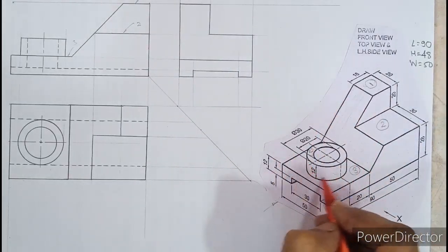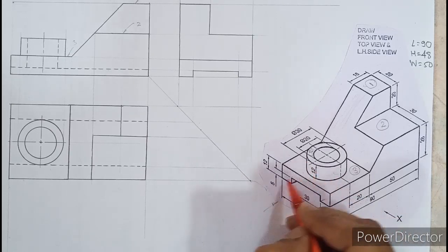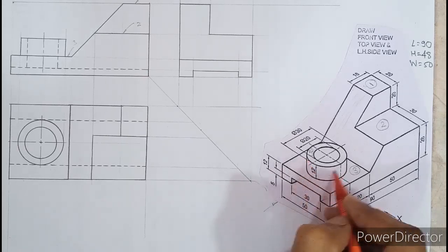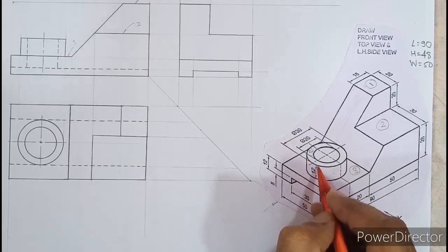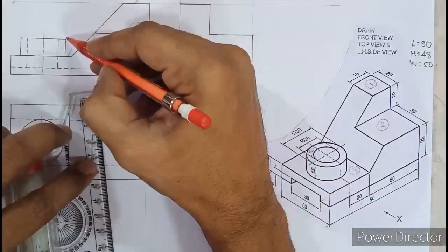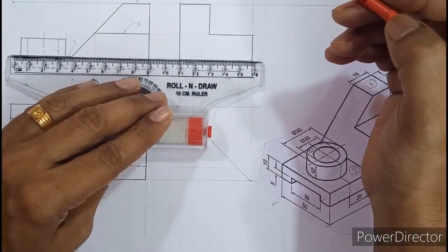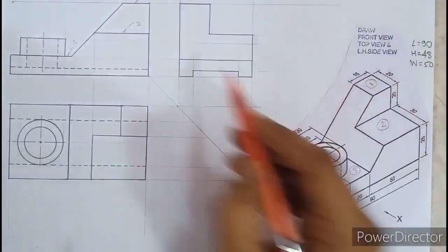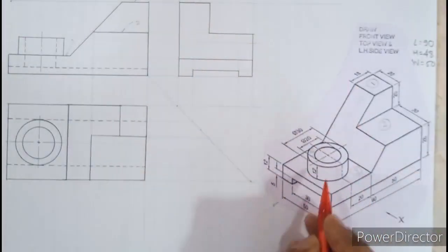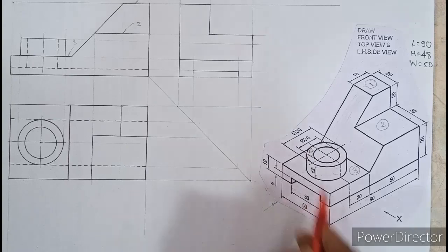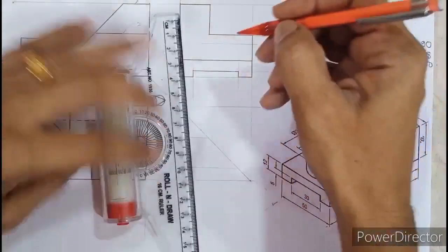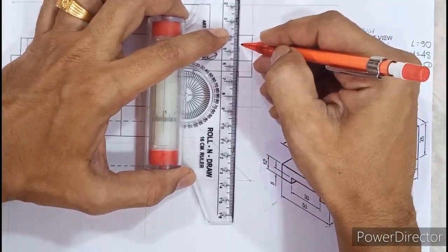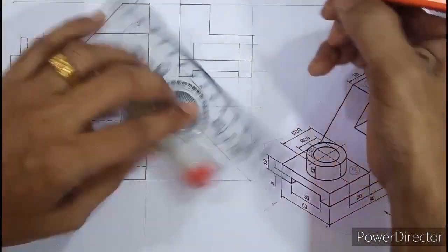The only thing what is left is the cylinder surface, which is 12 mm height. So what is the side view of the cylinder? Will it be seen as a circle or a rectangle? Yes, it will be seen as a rectangle of height 12, and height is always found in the front. So in the front, this height is 12. So from here we will project this. So 12 mm is ready. But what about the other position? Now see, little common sense, this is 30, right? And even this is 30 you have drawn. So if I just darken the required part, I can get that 30 mm.